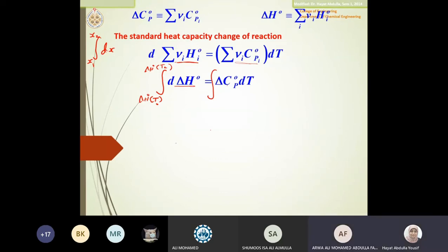Okay, good. And then now with the other part, what do I have? I have integration of CP dt. And then there is delta there, but let me just clarify. If I did integration of CP dt like this, how did we do the integration? Remember that the CP is a function of temperature. How we did the integration, I will remind you. We divided by R, multiplied by R, and then we said that the integration is equivalent to CP mean H delta T. This is exactly what we did because I need to find a mean representative for this integration.